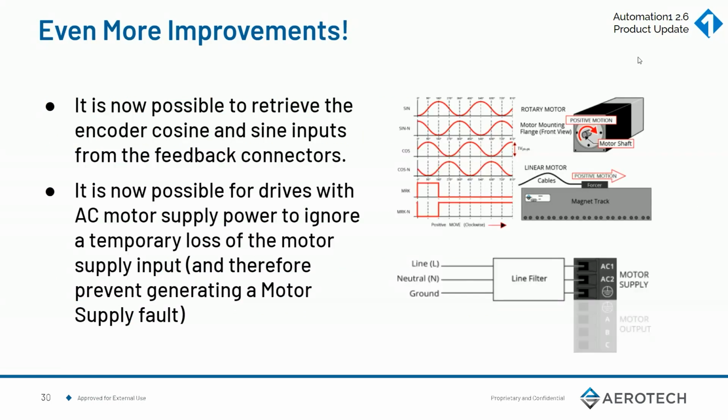It is now possible to retrieve the encoder cosine and sine inputs from the feedback connectors. Lastly, it is now possible for drives with AC motor supply to ignore a temporary loss of the motor supply, and therefore prevent generating a motor supply fault.